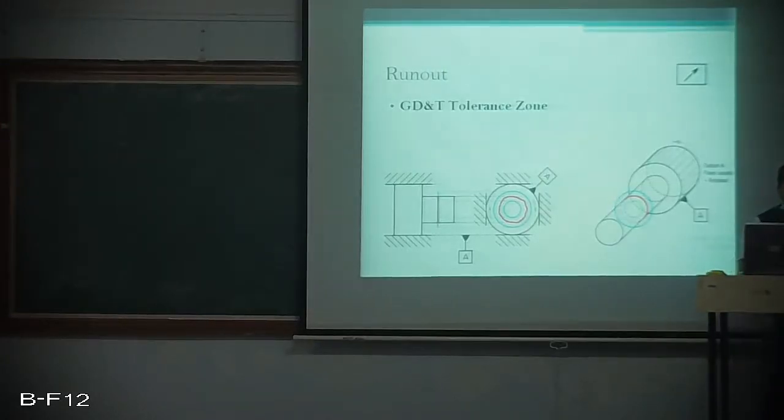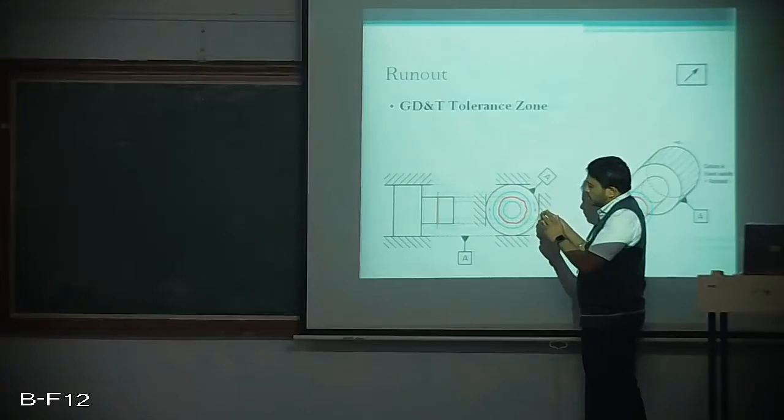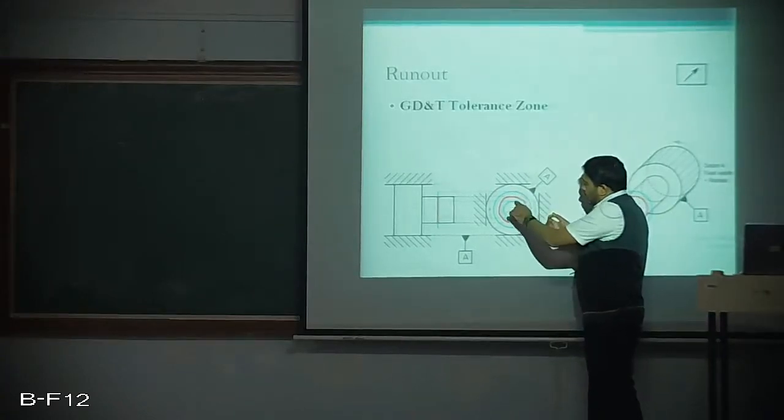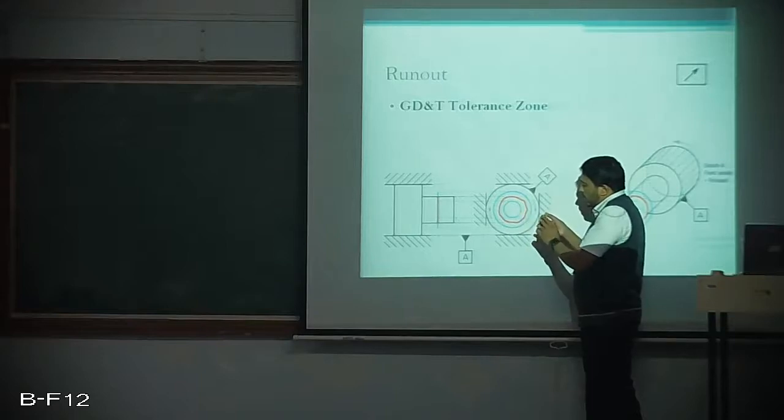See here, that is what it is showed over here. So this is the second step, and this is the first step. If the variation is this variation, this is the actual red line. This red line is nothing but this actual manufactured part. This black line is this part, and the blue lines, these two concentric circles, are the tolerance zones, which are specified with respect to this red manufactured line.